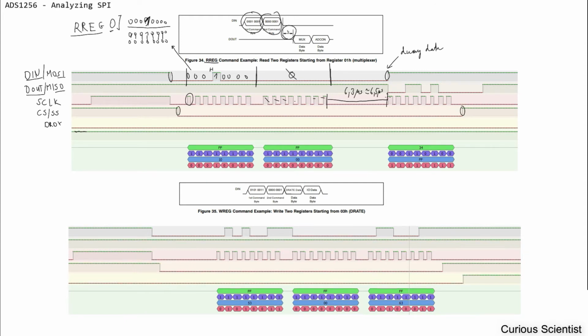So as you can see, when we clock, the first two clocks are 0, and then the third and the fourth clock gives us 1 for the D out, and then another 0, 1, 0, 0. So then this is the result, and if you convert this to a decimal number, then this will be 52.